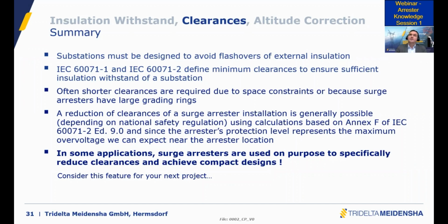The easiest way to reduce the residual voltage is, of course, to reduce the rated voltage of the arrester. But this then has an impact on the temporary overvoltage performance, so you want to make sure that the arrester can withstand the TOV values of your system. And of course, you can use different sizes of blocks.